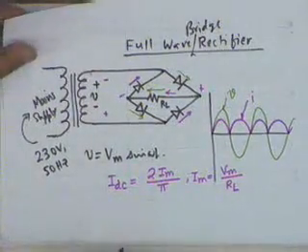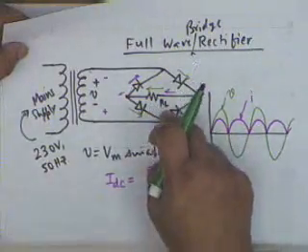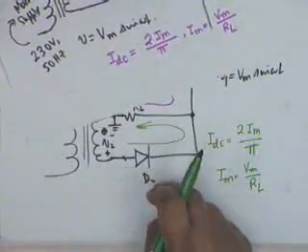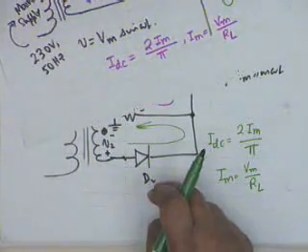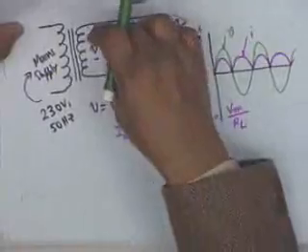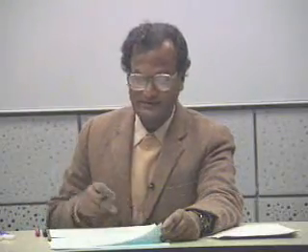So does it mean that this develops a lower voltage as compared to the 2 diode rectifier? Yes. If this Vm and this Vm are identical, then obviously the 2 diode rectifier develops a higher voltage, and this is where you pay the price. Effectively, it is the peak value of the voltage developed across half of the transformer, and the more the number of turns, the more you pay, because you use more copper wire, and more core, more iron, and you have to pay for the metal. All right. So this is an expensive proposition, but in critical applications this is what shall be preferred.